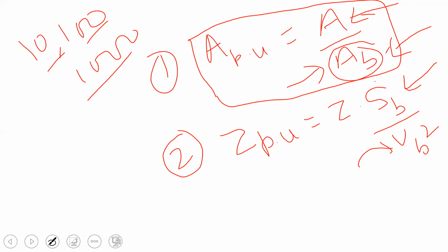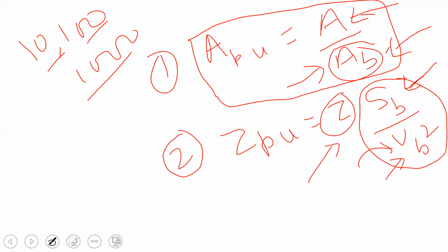And from where you will take these two values, I have already stated, you will have to consider them from the rating of the machine. On the machine, these two values are usually given, and the impedance value is given in ohm. Then by using the rating of the machine, you can convert ohm to per unit. So this formula is very important. You must remember this formula.